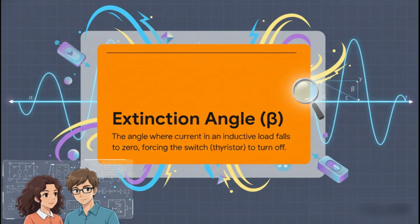The total time the switch is actually on is called the conduction angle, and it's simply beta minus alpha. With a resistor, beta is always a predictable 180 degrees, but with an inductor, it's always more than 180 degrees.